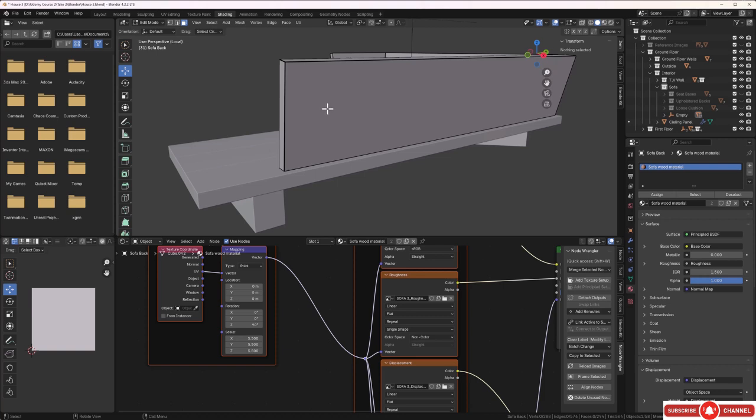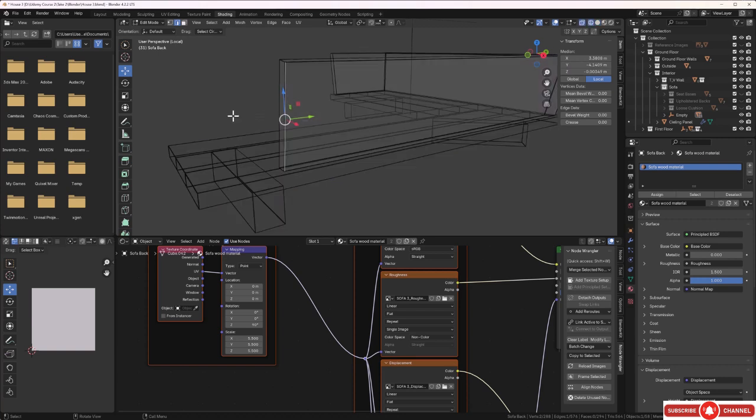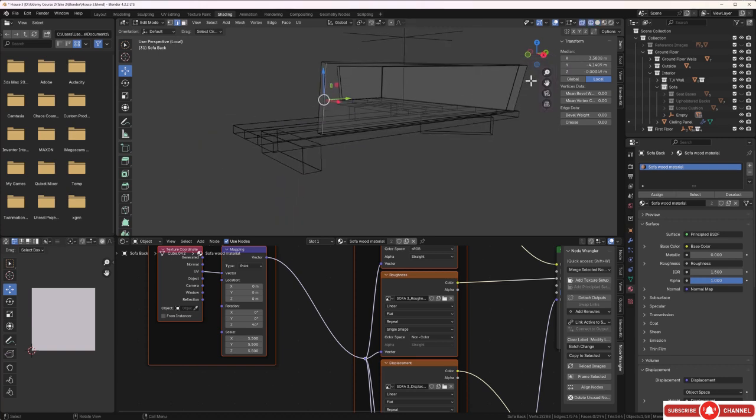So let's make sure we can select edges. So let's press 2. Let's grab an edge here, and we'll press Z as well. Let's go into wireframe. And I think let's go ahead and select all of these. Whoops. I'll go over here to selector, and I'll just hold down the left mouse button and come over to select box. That's better. And I'll select all of these like this, and I'll press Control R and see if we can get a loop in there. And it allows us to put 1 loop in, so that's a start.